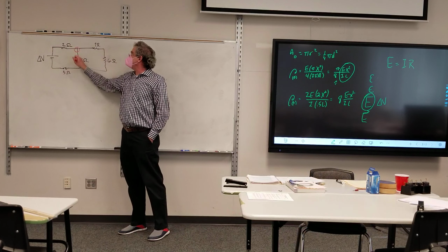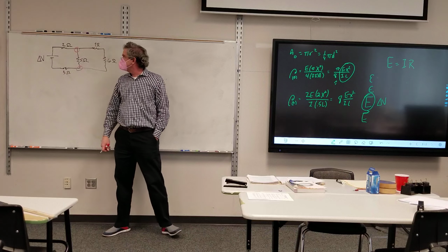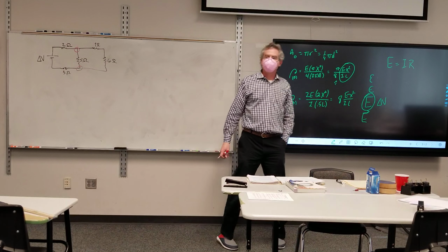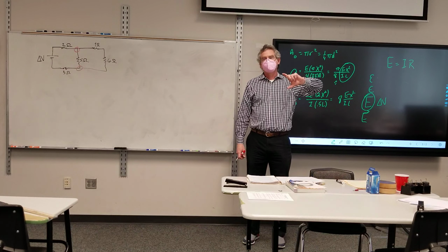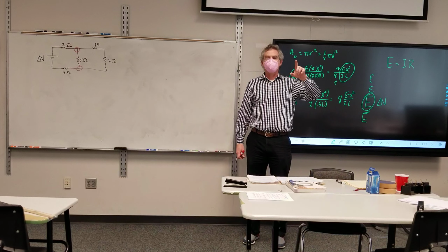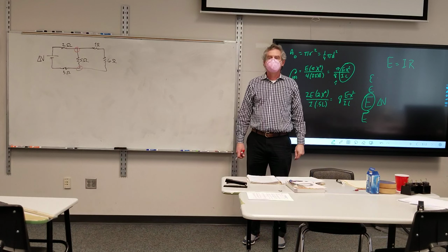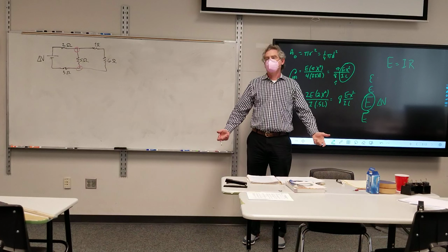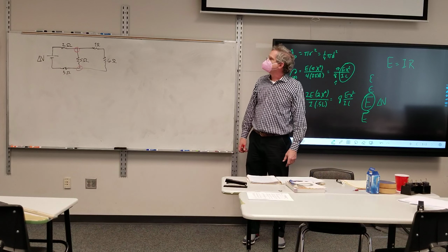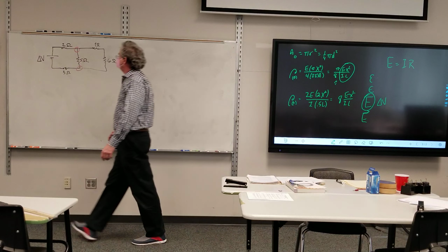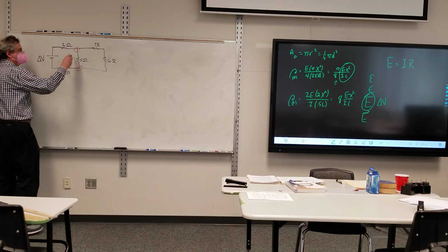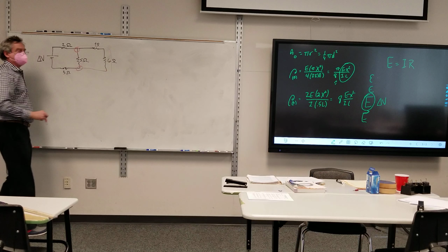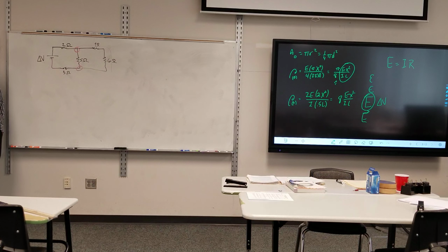All right. Figure out where the junctions are. Going from one junction to the other, is there any place where I'm going to pass by 2 resistors? Yes. Which path? Either of them, the 1 ohm and the 6 ohm, left or the right. Well, there's a battery in here, but yeah, I have to add those first before I do the parallel. And then that's parallel with the 5 ohm resistor? Yes. Great. You have to do the series first. Don't do 6 and 5 in parallel yet, because that 1 ohm is messing it up.